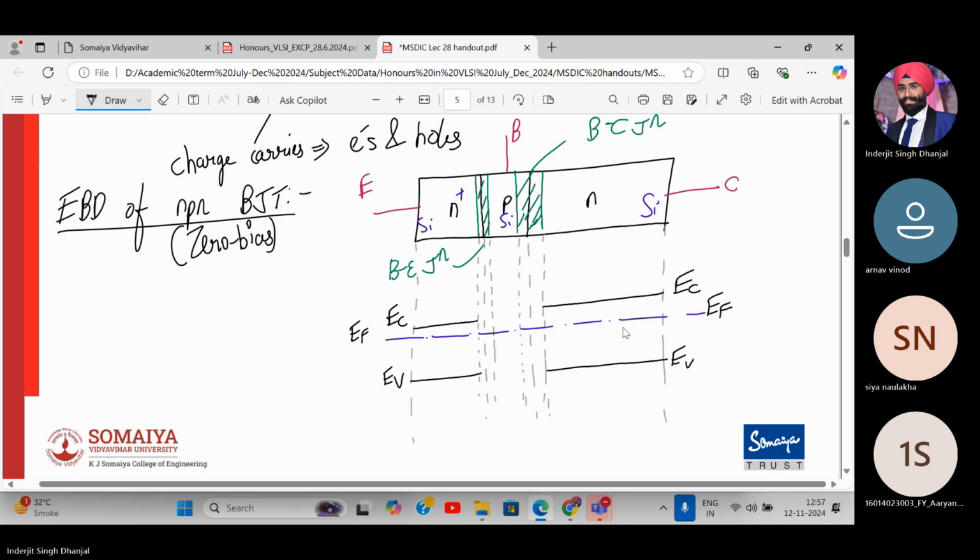EG. Now, where will the energy band diagram of the p-type silicon come? For the p-type silicon over here, EV will come near the Fermi level and EC will come above. Agree? So far, have you understood how to draw? Can I complete it? Yes, drawing, sir.